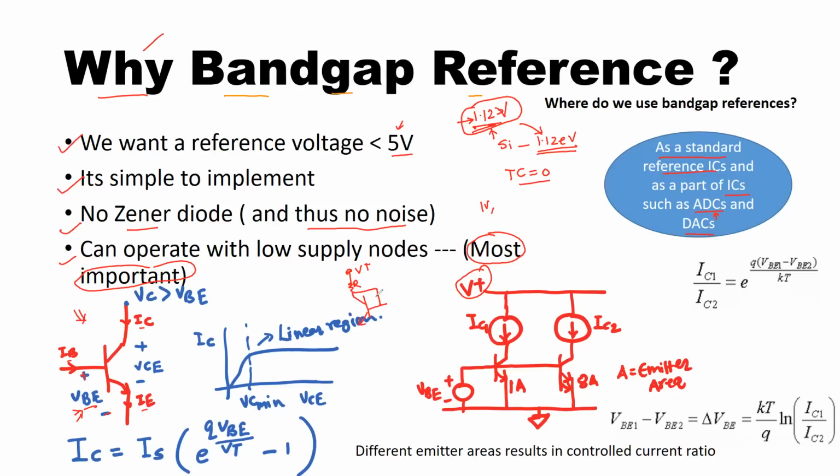Right here. So this transistor will always be operated in the linear mode or active mode. And then we just mirror this transistor's current into another transistor, let's say Q2. So we've seen that, and that's how we generate this I out, for example. But before I out, we are generating the VBE here. So we are forcing the current into the transistor to generate the VBE.